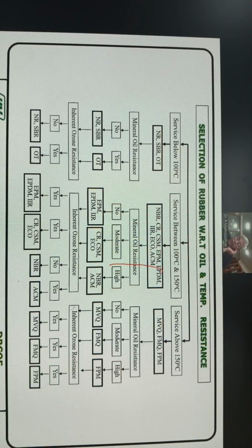So in this table, in the case of silicone also, there are different types: methyl vinyl silicone, fluorocarbon methyl silicone. Depending on the type of substituent on the silicone rubber, whether it is a vinyl group, a methyl group or the presence of a phenyl group, the properties of the silicone rubber also change.